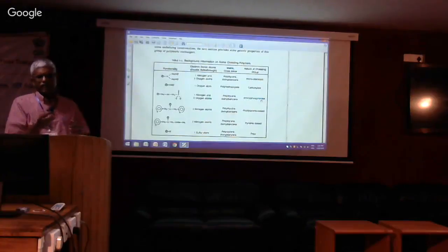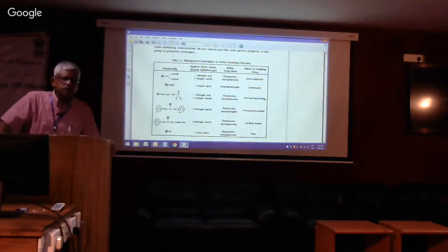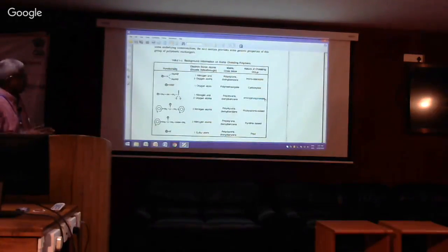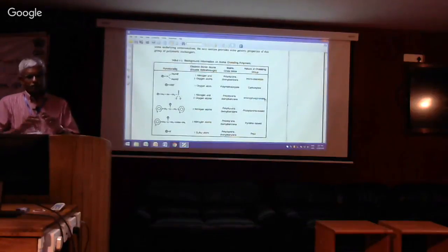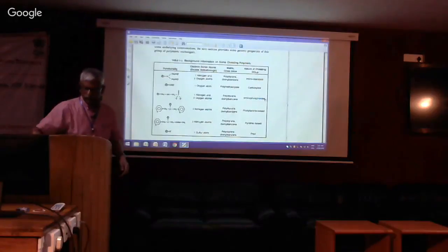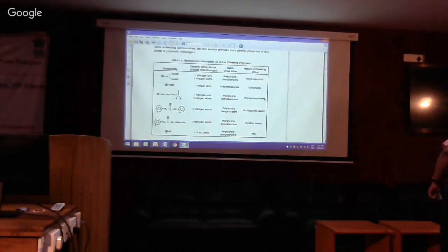And perchlorate is such a dangerous contaminant in terms of health effects if you drink contaminated water. The necessity of removing it is so high that we don't really regenerate the resin. These are called once-through resins. Once through means, as the name suggests,